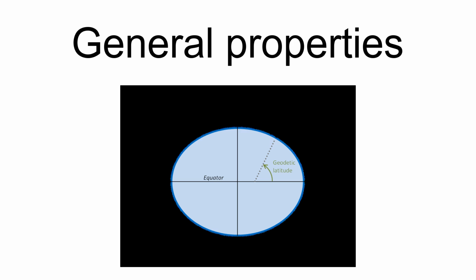For most applications, the surface is the reference ellipsoid of the Earth, and thus n-vector is used to represent a horizontal position. Hence, the angle between n-vector and the equatorial plane corresponds to geodetic latitude, as shown in the figure. A surface position has 2 degrees of freedom, and thus 2 parameters are sufficient to represent any position on the surface. On the reference ellipsoid, latitude and longitude are common parameters for this purpose, but like all 2-parameter representations, they have singularities. This is similar to orientation, which has 3 degrees of freedom, but all 3-parameter representations have singularities.